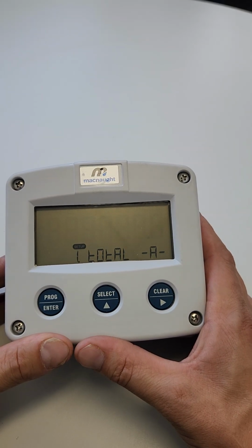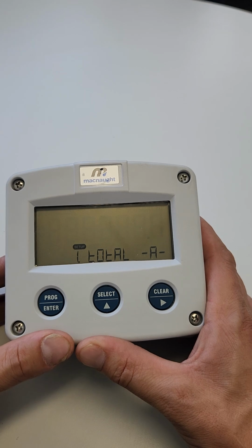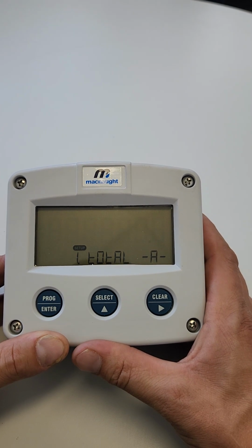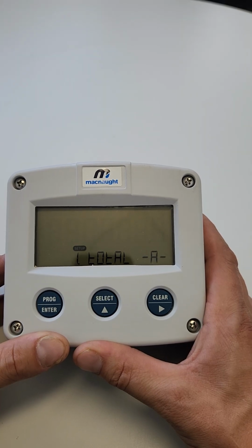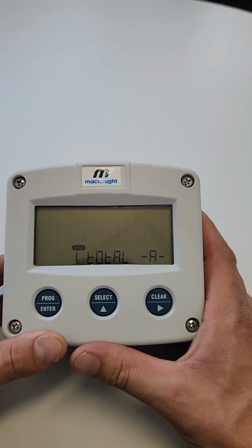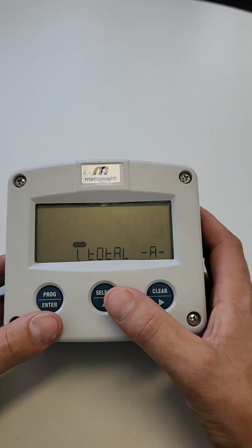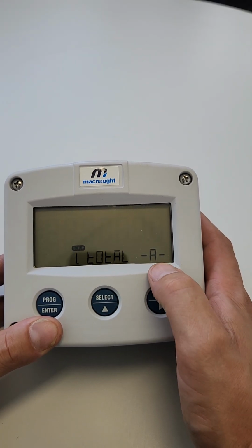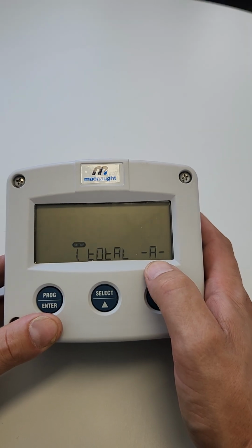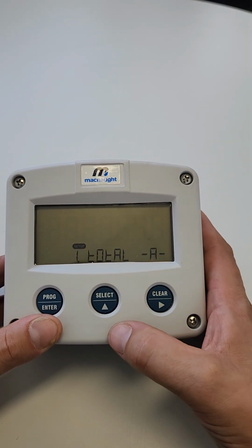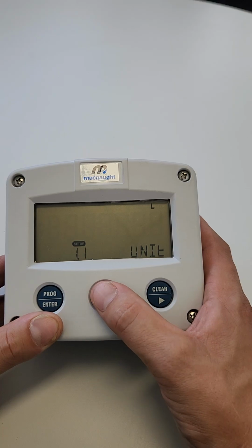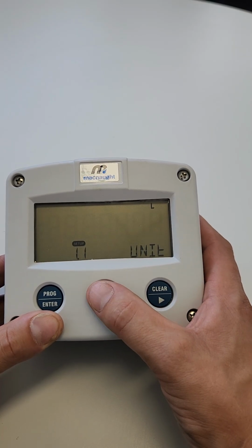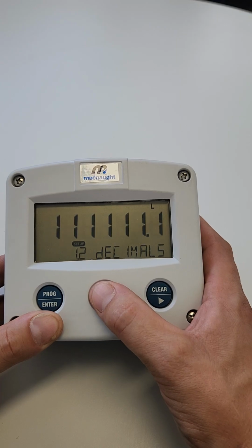which takes you through to the multiple settings, 1 through to 8 or 9, where we can enter in our different K factors and information we need to make it all work. So if you see here, we've got number 1 and we've got total A. Our total A, or our A input, will be our bulk diesel input. Our B input will be for our light vehicle diesel. If you hit the up button, it'll take you through all the settings in number 1, which has 4 different settings in here.